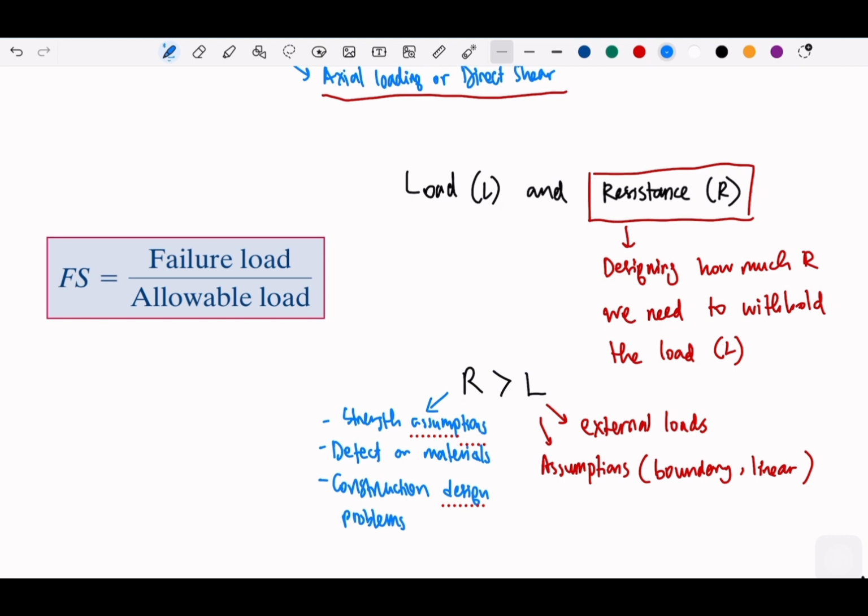So we need a safety factor that we multiply, so that we are sure this should be safe. For example, take the elevator. It's rated averagely for 10 people. I believe if you push 12 or 13, it could stand. But for design safety, we limit it to 10, because we want to make sure the elevator can withstand for some period of time before maintenance.